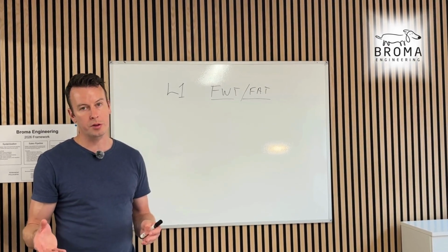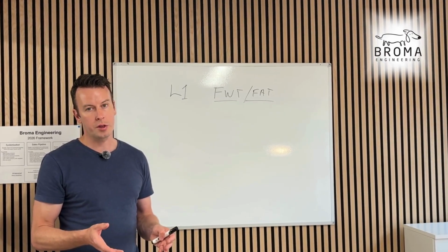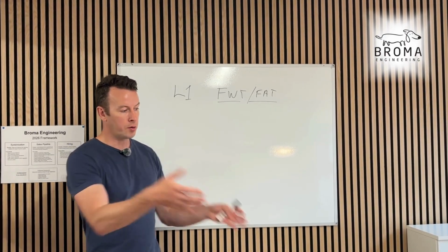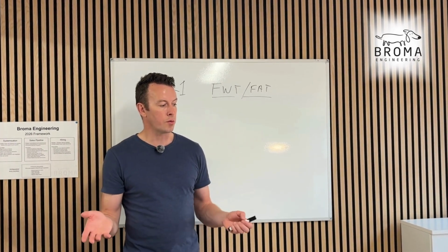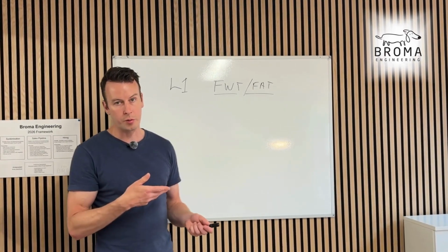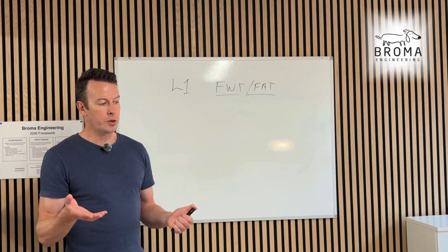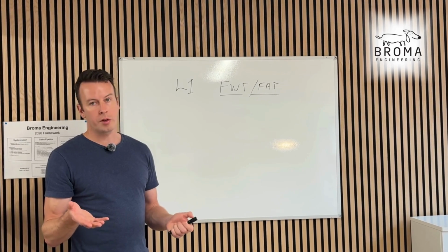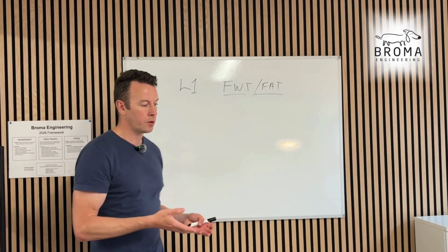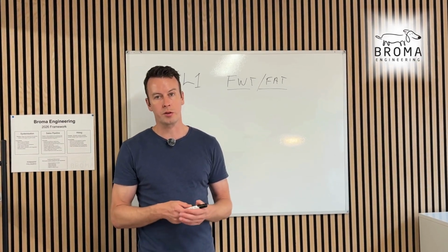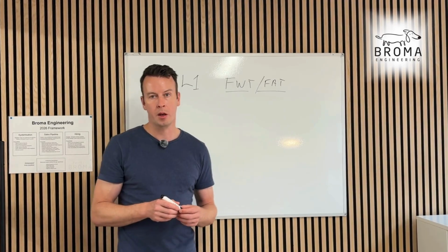So you have to talk to logistics, have to talk to your CSA friends. Is the ground outside strong enough to roll the truck up to it? We're probably not going to be using a loading dock for this, it's too big. Is it upstairs, is it downstairs? Do we need to crane it over anything? Do we need to close off areas? So that's going to impact other works, it's going to slow them down. So you need your scheduler involved with this as well.